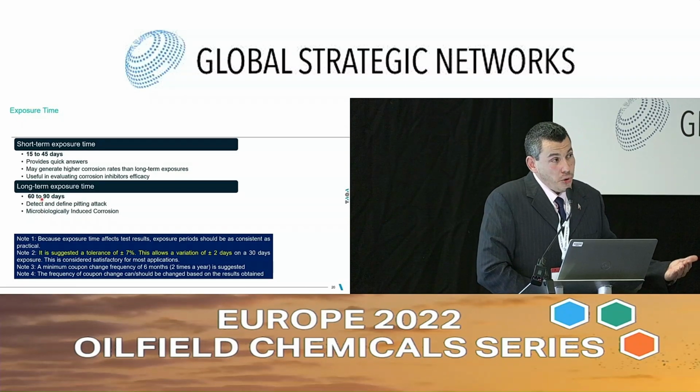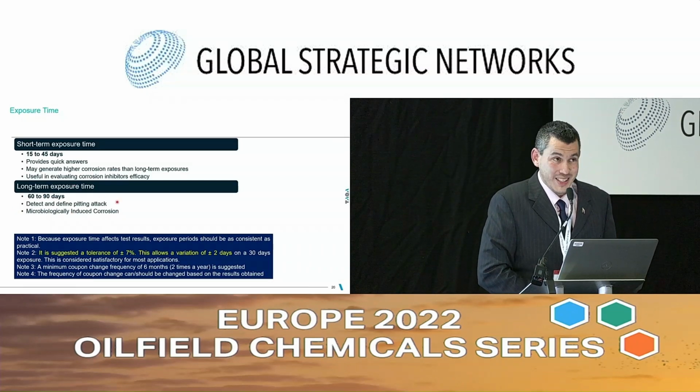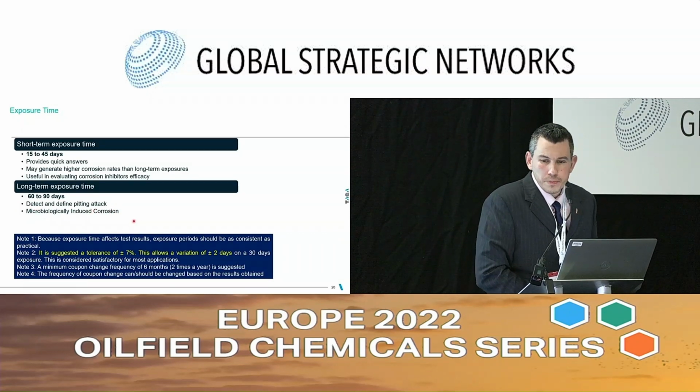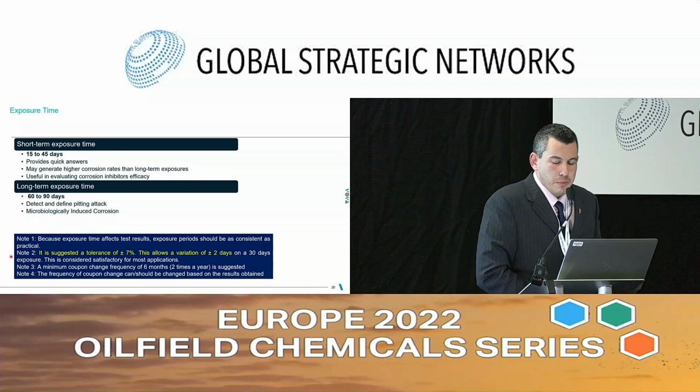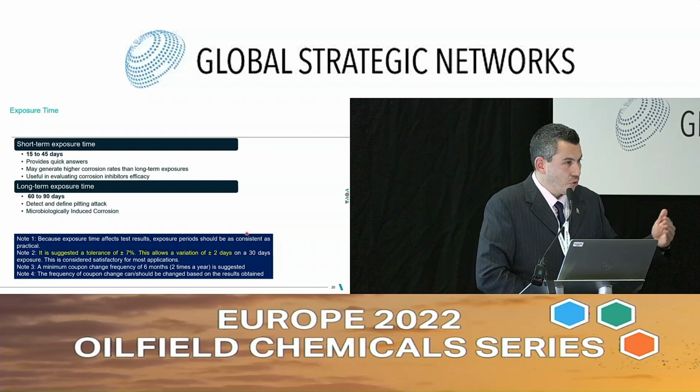There is another approach, long-term exposure time, between 60 and 90 days. You can detect and define pitting attack, and you can also assess microbiologically induced corrosion. There are a couple of notes and remarks that I want to mention here. So the first one is that because exposure time affects the test results, you want to be as consistent as possible with exposure time.